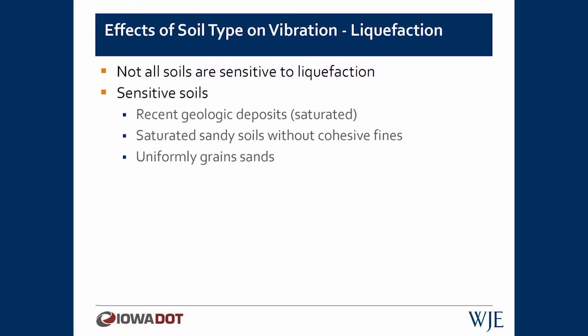Then again, not all soils are sensitive to liquefaction. There are some sensitive soils. It was referred to as recent geologic deposits that are saturated, such as river sands that have not experienced any consolidation activity. Saturated sandy soils without cohesive fines. It's something that we'll get into a little bit. Uniformly graded sands.